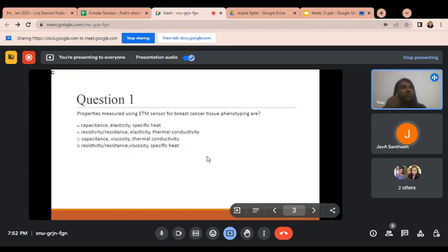After we grow the oxide on top of the silicon wafer, we will pattern transfer the IDT pattern. We need an electrode now on the front side. So tell me, how do we deposit the gold? I have already told you about the deposition process. Can you name any of the deposition processes?